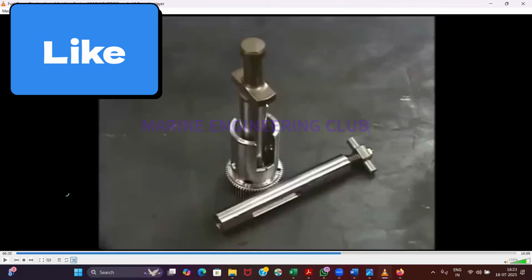When all these 3 markings are aligned during boxing up, that means your pump is having zero setting. And zero setting is that setting of the fuel rack where effective stroke is zero. I will come to this, but first understand this: when all these 3 markings are aligned, that is zero setting of the fuel pump. Is it clear? Okay, yes sir.